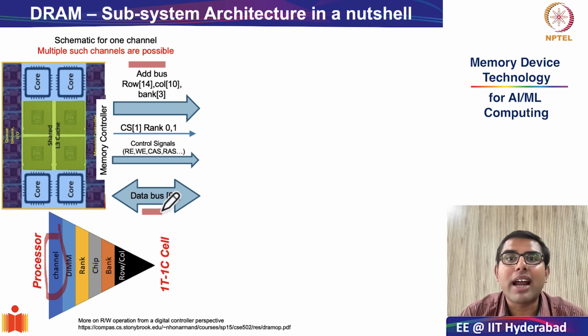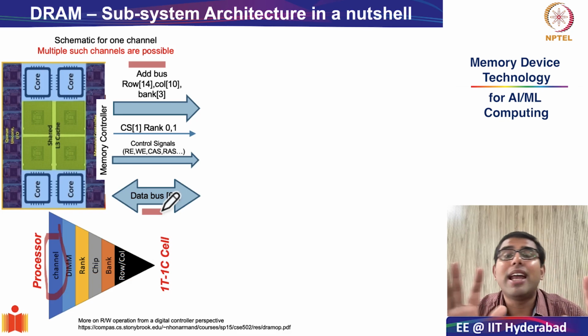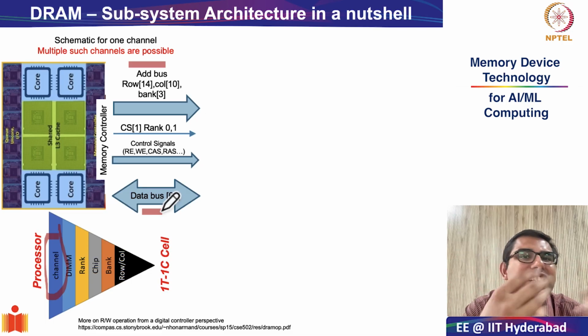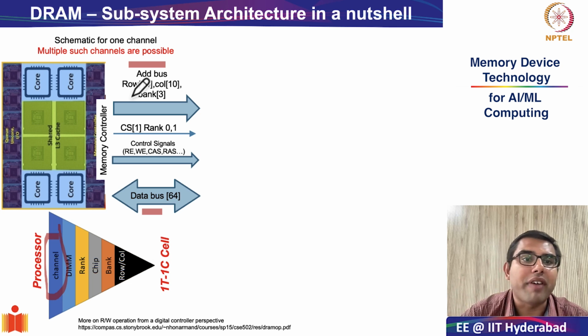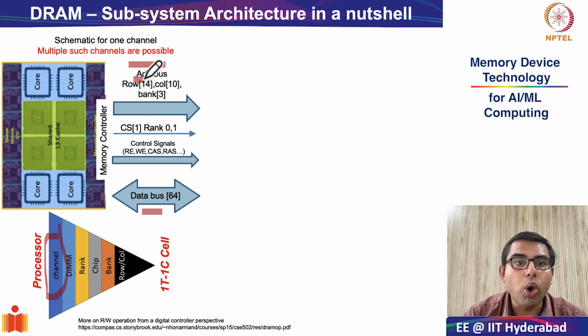Even in the von Neumann architecture, we had broadly classified that it consists of logic and memory elements which are spatially separate. We just see another implementation of the von Neumann architecture over here. The address bus consists of 3 main components because it is supposed to bring out data from memory locations which require 3 different aspects of address. The first is definitely the row and the column address.